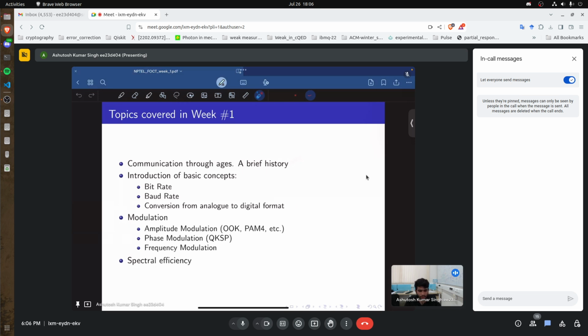The fiber is between your home and the nearest access point, and from the next access point to the metro area. So if I draw it, let us say this is the cell phone, and that is talking to a tower there, but after this, for last mile connectivity, everything is connected by optical fiber. The reason for use of optical fiber is because it has low loss as compared to other methods. It is cheap and it has very high bandwidth.